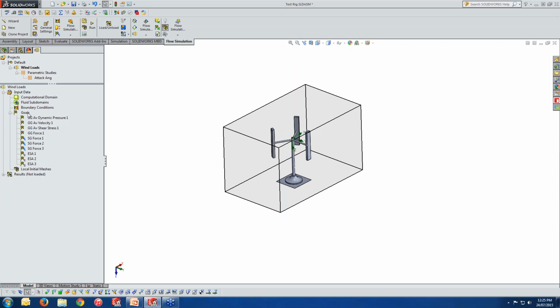This comes down to a series of goals you are simply defining. If you are interested in looking at the convergence and variation of a parameter, then you can right click on your goal. Either you would like to trace it globally, or at a point, or at a surface, or over a volume. Also, if you have your own equation to be traced, then you can insert the equation code. This is exactly what I've done.